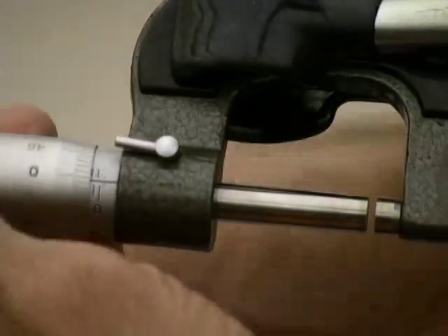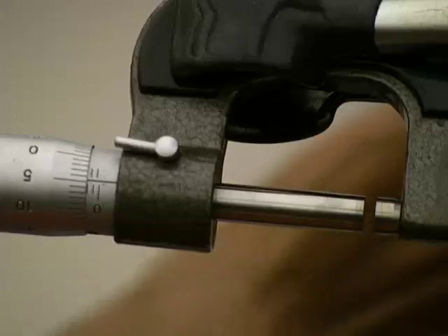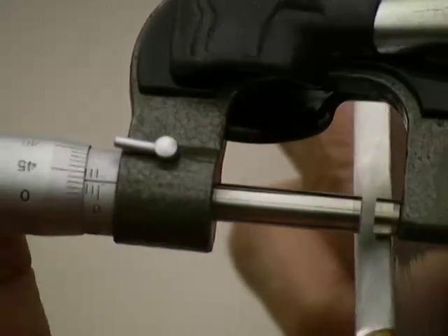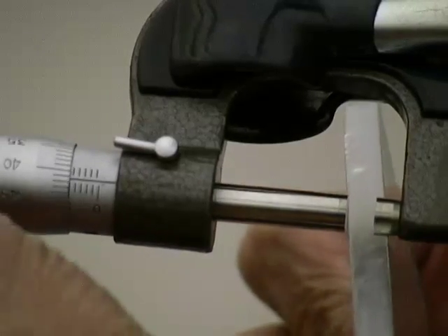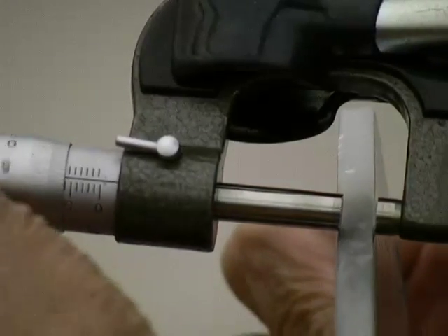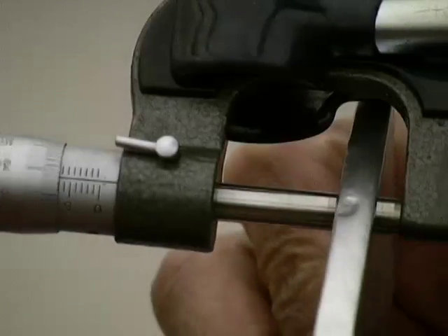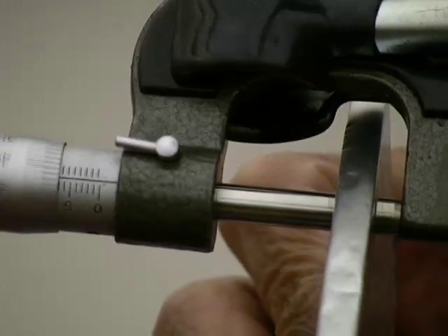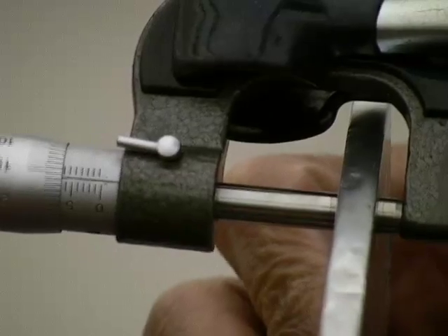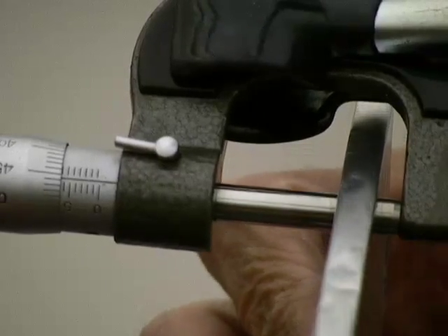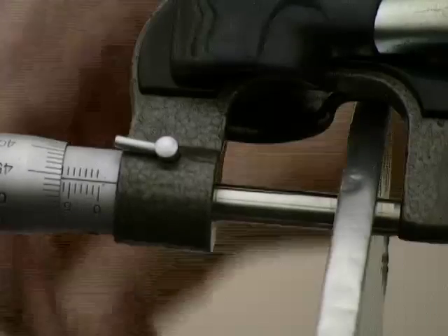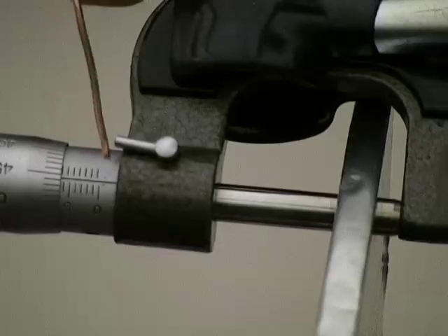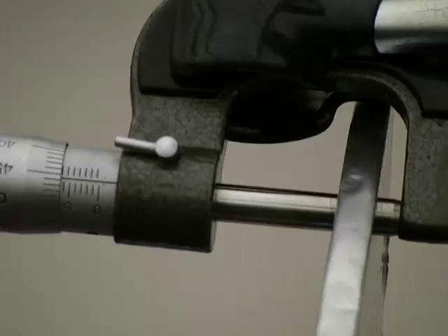So, if I want to measure the thickness of one of our materials, I will work the screw back to create the space, and I will insert the material in that gap. There you are. And work the screw back until I hear that tick sound, which means it is firmly gripping there. Now, I want to measure the distance moved by the round scale along the linear scale.